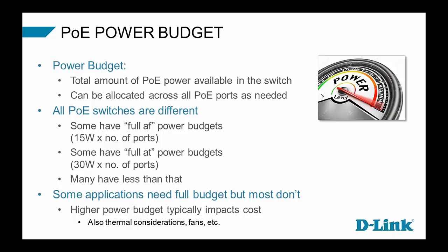And keep in mind, a higher power budget in the PoE switch typically is going to impact the cost, higher cost. May also have thermal considerations. We have a PoE switch with a 65 watt budget, has no fans. It doesn't need fans for cooling, so it's silent. Our PoE switch with a 370 watt budget, of course, is going to have fans in it. When it's providing that much power, it needs to do some cooling, so it's going to make a little bit of noise. So there are other considerations as well when you're looking at PoE power budget.